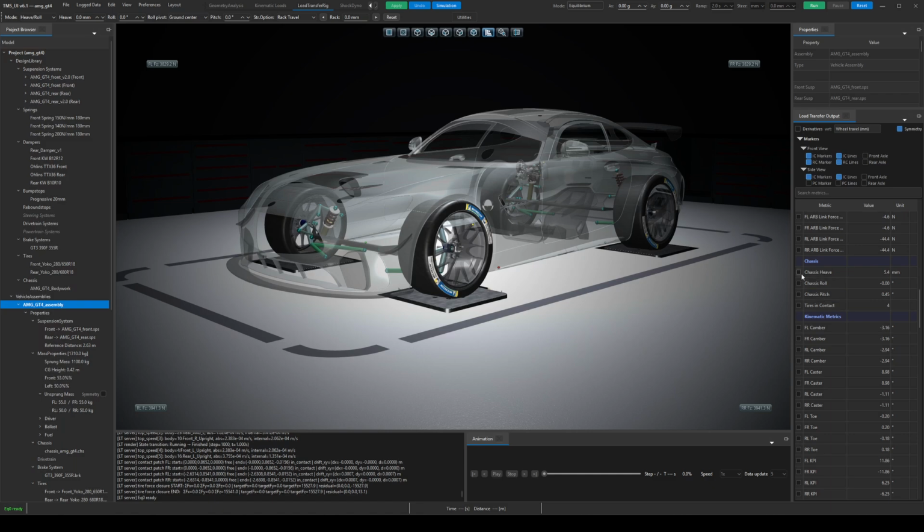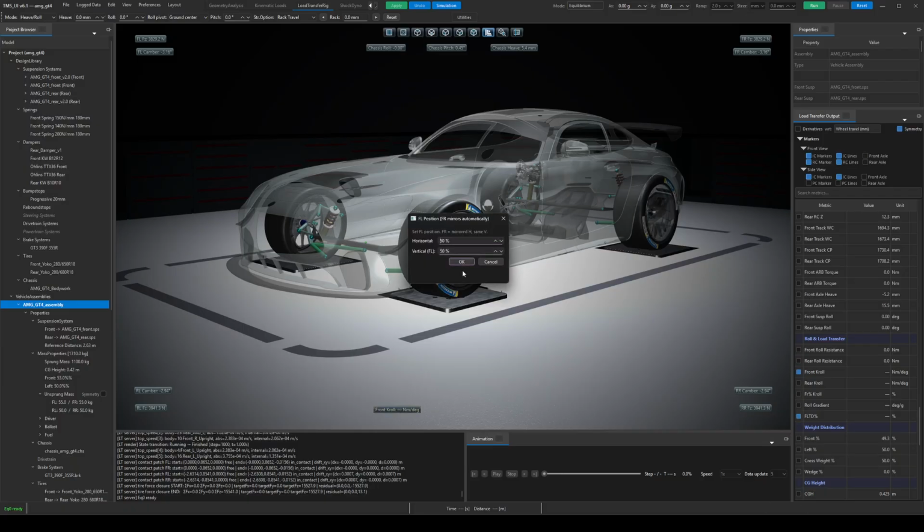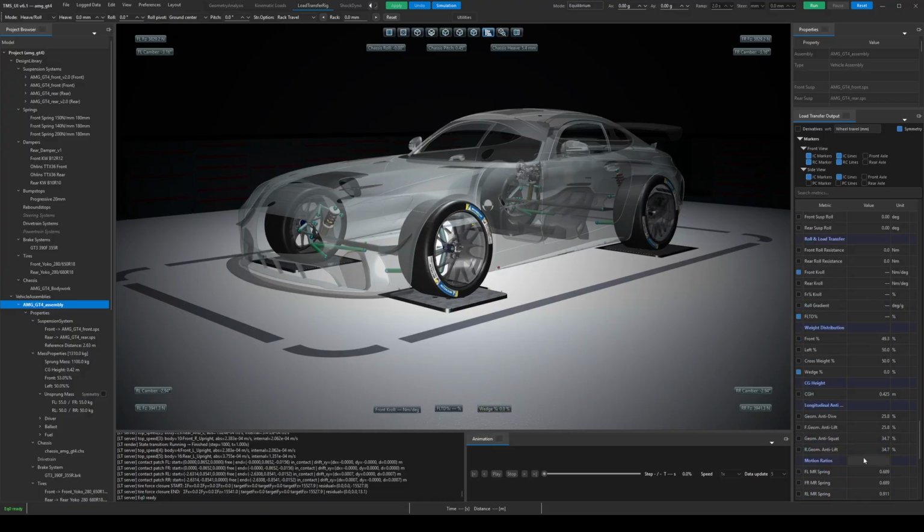In very basic terms, the tire forces at each corner are linked to vertical load and acceleration. The longitudinal tire force equals the vertical load times the longitudinal acceleration, and the lateral tire force equals the vertical load times the lateral acceleration. This is an oversimplification of the actual implementation, but it explains the main idea. Longitudinal acceleration on the driven axle is applied according to the drive torque distribution. Braking force is applied according to brake bias, calculated from brake pressure bias, front and rear piston areas, and effective disc radius.